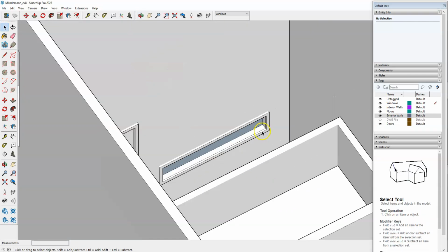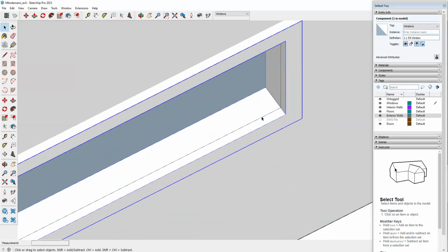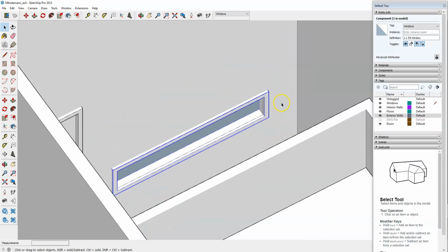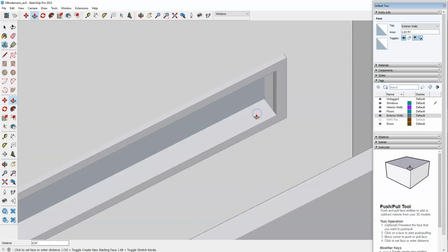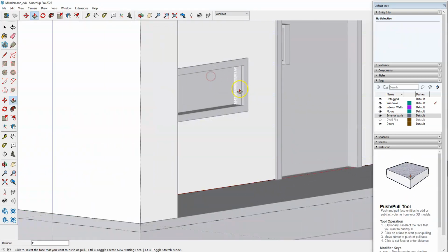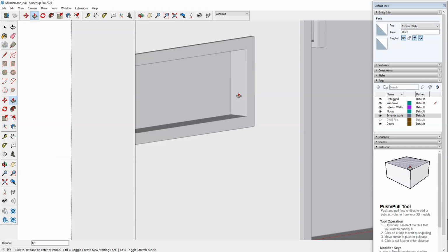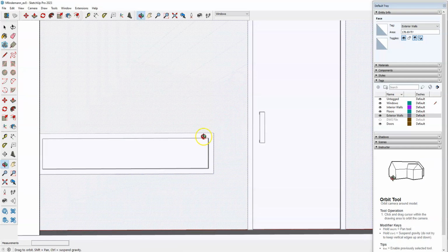Looks good. And again, we can do the same thing if these lines bother you. This line here is the exterior wall coming through. So if you want to go into your exterior walls and push those surfaces down maybe 1 inch or so, or push them away from your frame, it's totally fine to avoid these overlapping planes. So I'm just pushing them 1 inch away.